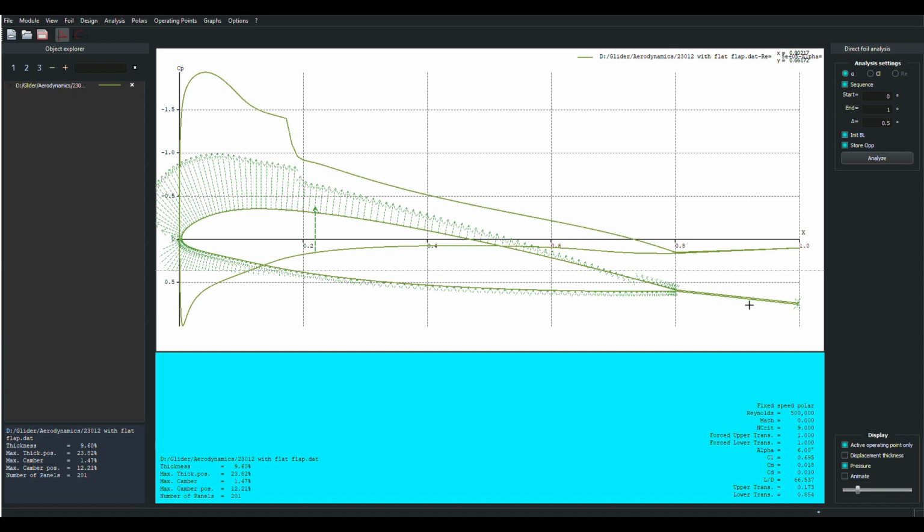But there's essentially nothing happening here other than the flow cruising along at very, very close to the free stream velocity, because we've gone all the way through the adverse pressure gradient, and we're here at nominal free stream flow conditions at the trailing edge of the airfoil, yet we still have this flat plate to go along, and it does that quite easily.